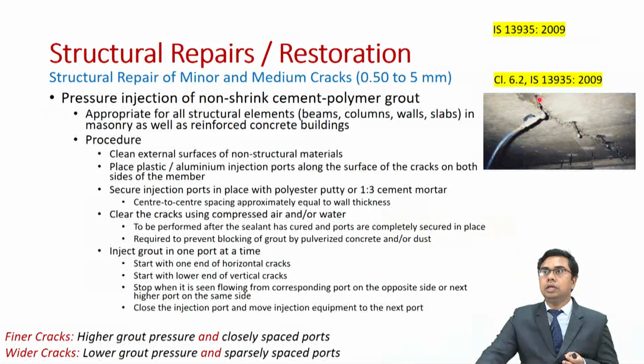Then we are securing these injection ports in place using polyester putty or 1:3 cement mortar. The spacing between these ports is very important. So, the center to center spacing should be approximately equal to the wall thickness.